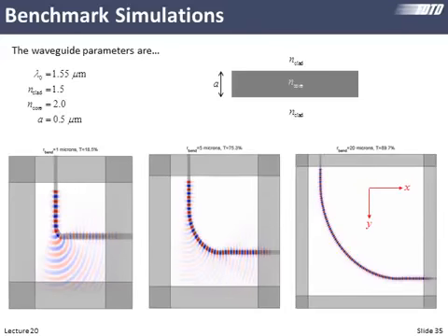So when the bend is 20 microns, we see that the transmission is about 90%. So 20 microns, that's huge. And this is a big problem in integrated optics, is that these waveguide bends need to be huge so that we don't lose light. And there's actually been a lot of research looking at photonic crystal waveguides that can do very tight bends without losing power. So anyway, use these if you build this type of code to benchmark yourself and see if you get these same types of numbers.